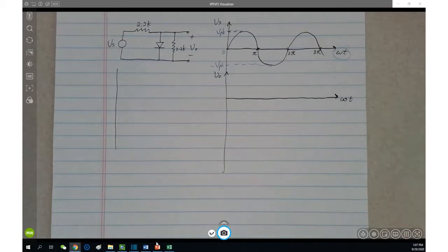And for the diode off, that's the second state, so a second circuit to find what V0 is. Respectively, the two states of the diode give two different circuits. Okay, so now let's follow Shane's idea. Let's begin with trying to identify in which time window the diode is on. So in this circuit, what do you think? When is the diode going to be on, and why? Anyone can tell?